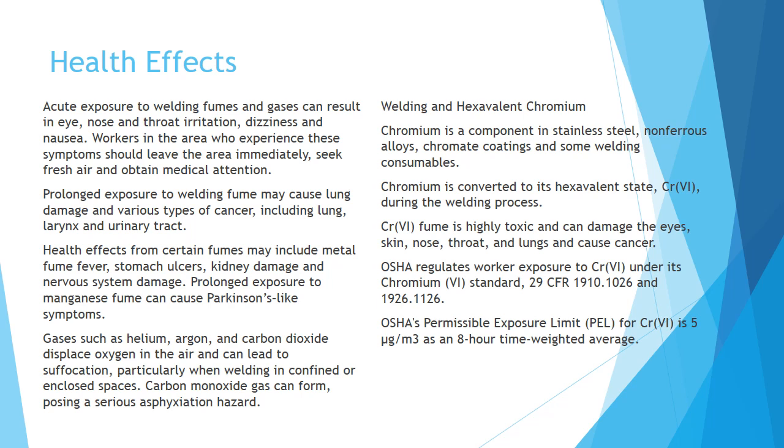Prolonged exposure to manganese fume can cause Parkinson's-like symptoms. Gases such as helium, argon, and carbon dioxide displace oxygen in the air and can lead to suffocation, particularly when welding in confined or enclosed spaces. Carbon monoxide gas can form, posing a serious asphyxiation hazard. Welding and hexavalent chromium.